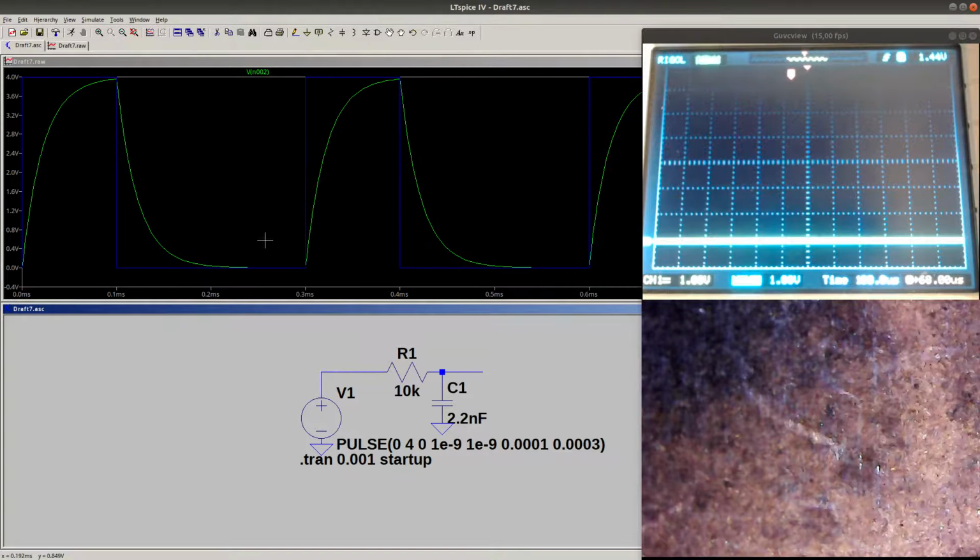So from this picture, I can already tell what the time constant of the system is, and that would be the time it takes for the output of the system to reach 63% of the maximum output. So 63% of 4 volts would be around 2.52 there. So the time constant is somewhere in the range of, let's see, can we see what that is, of 8 milliseconds.